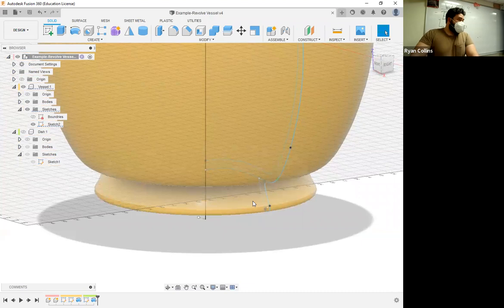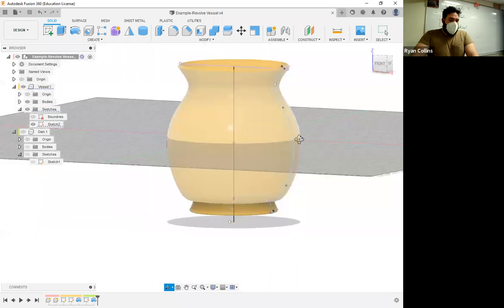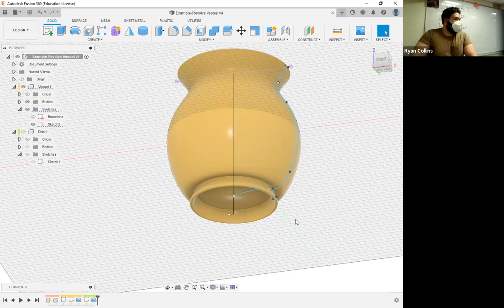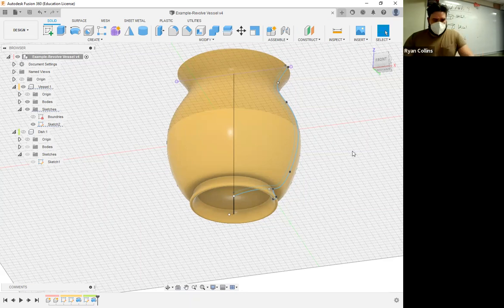So next up, I need some drain holes. Now, a couple things. How many and what size, any of that, is totally up to you. So let's say, just for basics, I want to draw an array of circles. I could do the center circle or multiples. I'll show you both. How to do that? Well, I'm going to use the sketch and extrude. So basically, just like you did for the badges, only when I extrude that sketch upwards, instead of making a body, I'm going to use the cut feature off of that and chop those holes out of the vessel here.